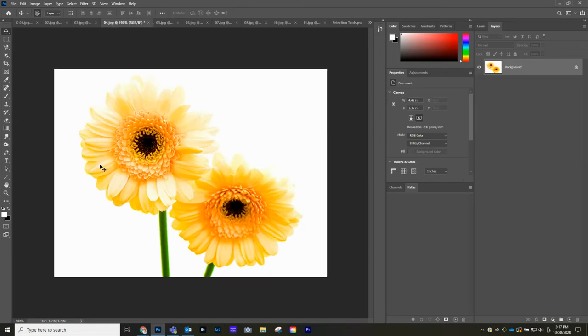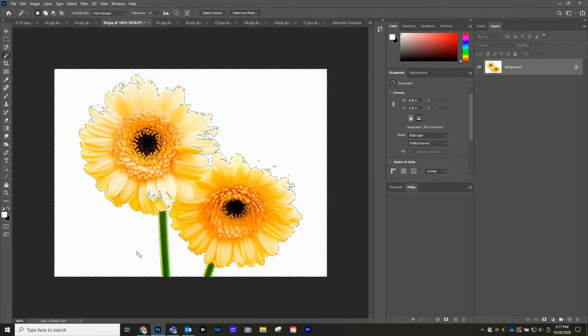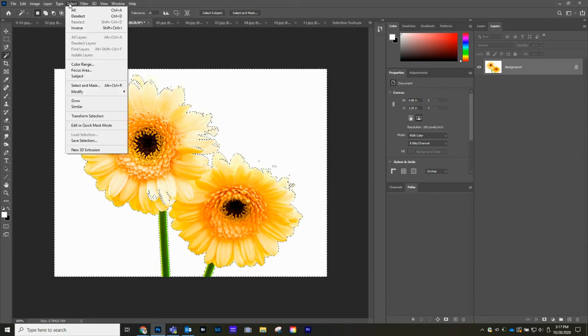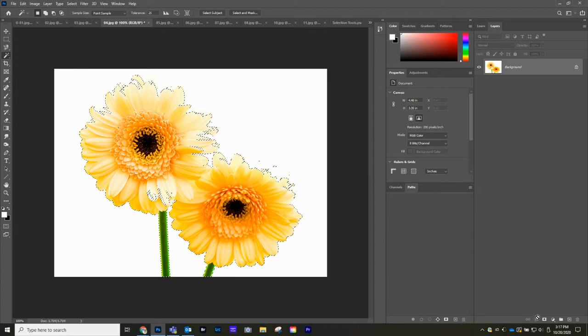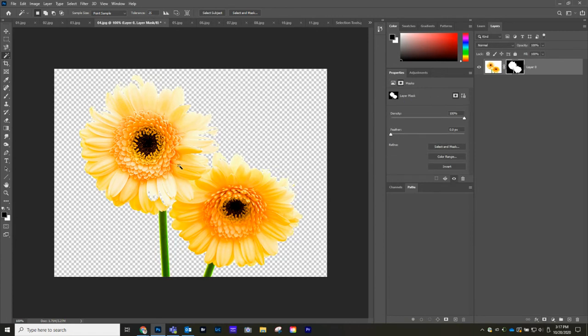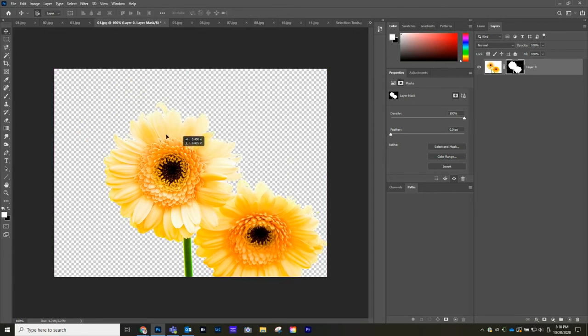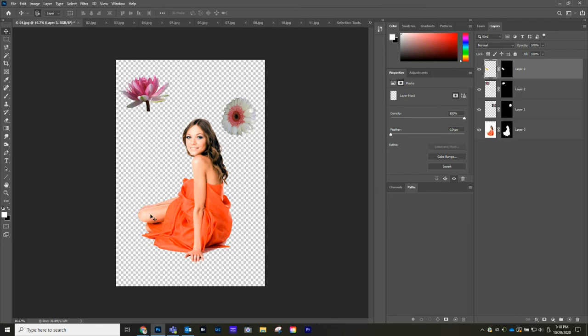This one I'm going to do a little differently. I'm going to switch over and use the Magic Wand tool. So I'm going to select the white, and then I'm going to go select. So I've selected the background. Now I want to select the flowers. Select inverse, and then mask it. So now if I go to my brush, I'm on the mask. Okay, so because I'm on black, I'm brushing away. Let's push X, and then I'm going to go in there and fill in that space. So this is probably going to get put behind something. I'm not too concerned if the selection is a little off. Let's just go ahead and bring it in there. Well, that came in pretty small. Okay.